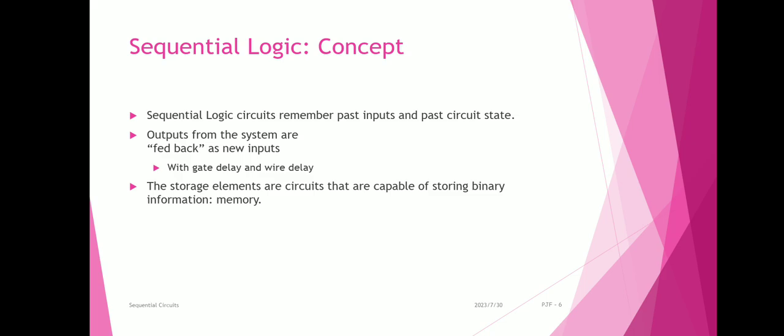The major advantage is its simplicity. The logic gates which perform operations on the data require a finite amount of time to respond to changes to their inputs, which we call delay. The interval between clock pulses must be long enough so that all the gates have time to respond to changes, and their outputs settle to stable logic levels before the next clock pulse occurs. As long as this condition is met, the circuit is guaranteed to be stable and reliable.